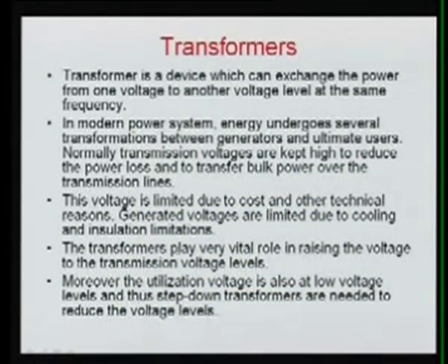that is very widely used in the power system, because whenever you require a voltage step up, or at the same time a voltage step down, we have to use it. We know the generation voltage is limited due to insulation. So we are able to generate only at a certain rated voltage, and presently it is not more than 21 kV in our country. If you transmit a bulk amount of power at 21 kV, you require several lines, and there will also be huge loss in the power system.